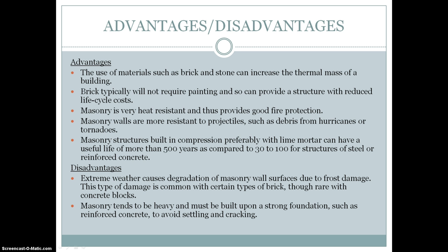And then masonry tends to be heavy and must be built upon a strong foundation, such as reinforced concrete, to avoid settling and cracking. So when you're building a structure that is made of brick, you may have to add in initial costs for the foundation as well.